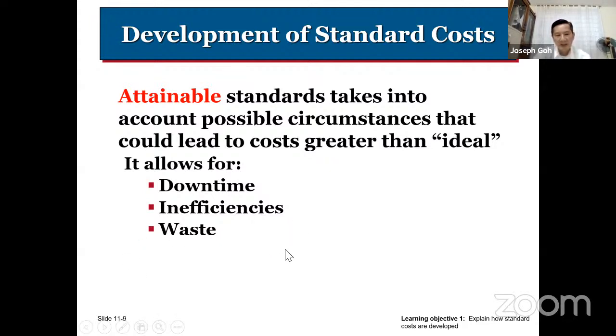A machine that's running 24 hours every day can also face some downtime due to some old part that needs to be replaced. So we take the data, we do the study, we think that the machine will run, but the machine also needs to tolerate 5% downtime. And we say the workers maybe have 5% no attendance. We also think that on raw material we buy, maybe another 1% defect. So we take all this into consideration. Then we build out the attainable standard. Yeah, attainable standards.